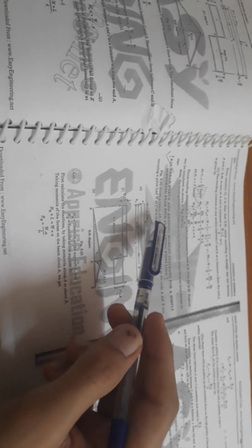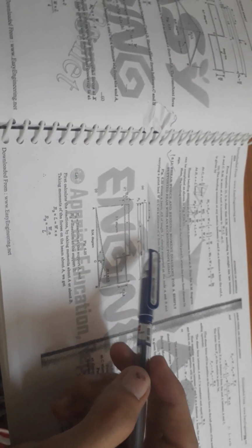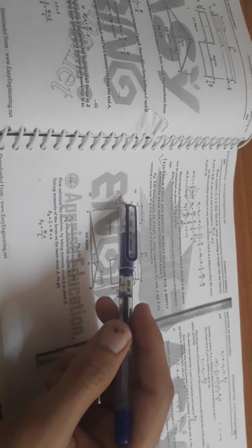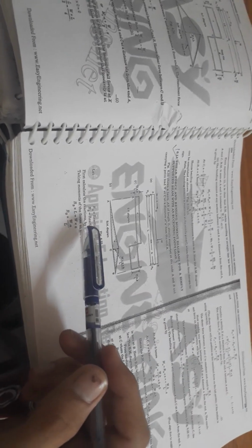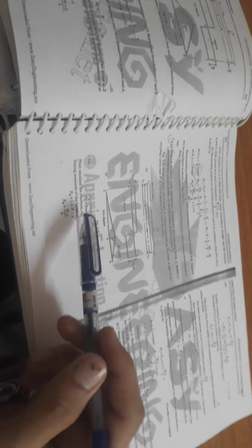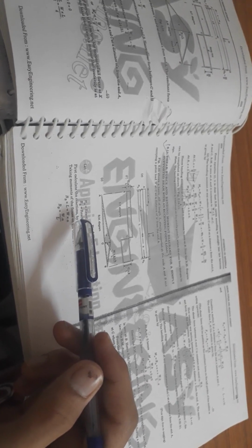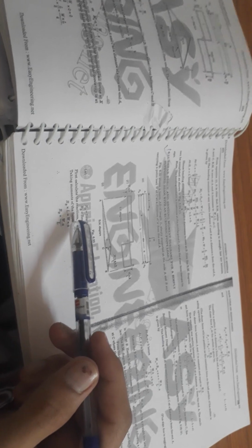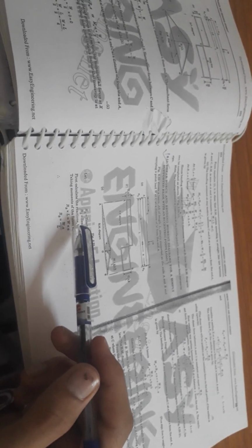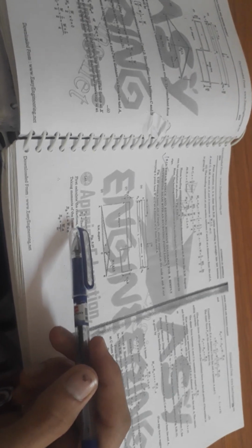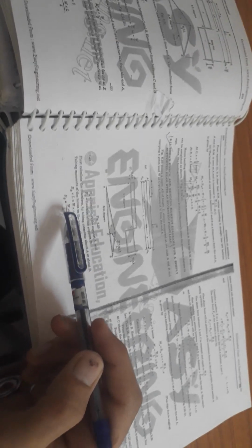Here it is W, here it is small x, here it is capital X, it is A, it is B, it is length L, this is RA, this is RB, this is W into B by L, this is W into A by L, this is W, this is the shear force diagram, and this is the bending moment diagram, W into AB by L. Here RB into length L is equal to W into A, then RB is equal to W into A by L.